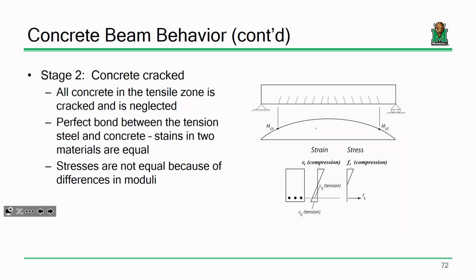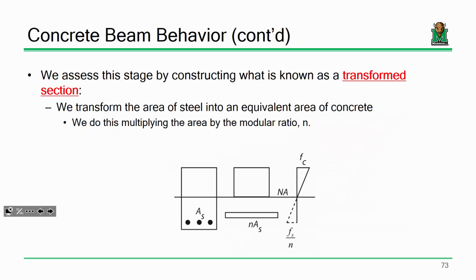Now, also, let's be clear. Beams can resist loads far beyond their cracking moment because of that rebar. Okay? Does that kind of make sense? All right. Everybody else okay with that? Okay. So we are basically assuming that the concrete in tension really isn't doing any good. What is taking over is steel.